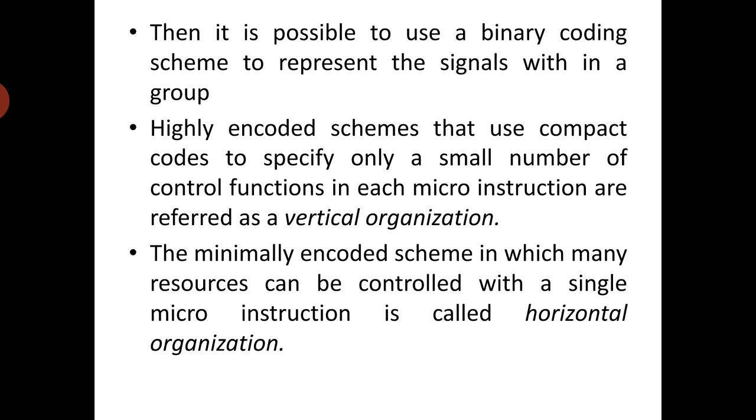The vertical approach results in considerably slower operating speeds because more microinstructions are needed to perform the desired control functions, although fewer bits are required for each microinstruction. This does not imply that the total number of bits in the control store is smaller.